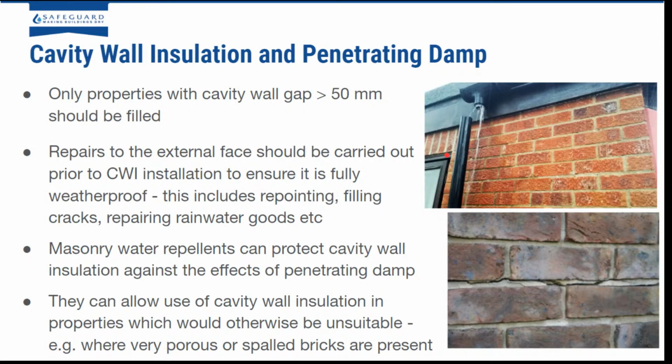So how do we avoid these pitfalls? Only properties with a cavity wall gap of greater than 50 millimetres should be filled as standard, and repairs to the external face should be carried out prior to cavity wall installation to ensure it's fully weatherproof. So this includes things like repointing, filling cracks, repairing rainwater goods, all of that kind of stuff.